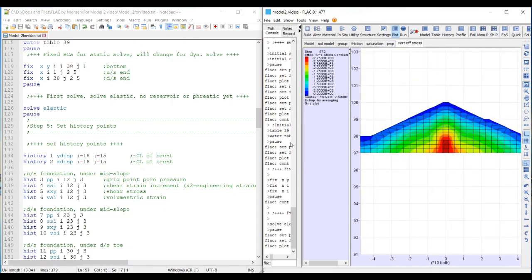So what someone could do here is, you could find a lateral coefficient, or earth pressure coefficient, and plot that up, and that would probably be a reasonable thing to do. I'm not going to do that in this case, but at this point you could do that. This isn't the final initial static stress. We have to add the phreatic surface, the reservoir pressure, and some other things.